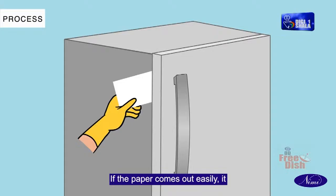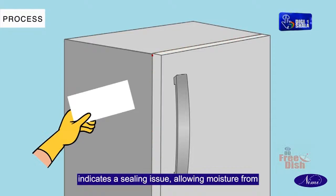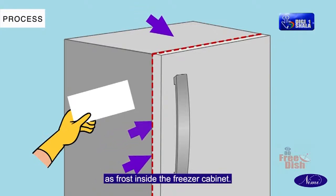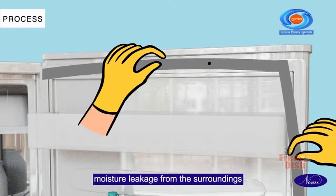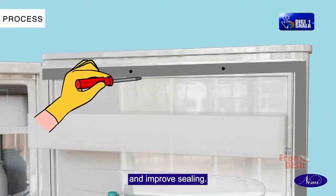If the paper comes out easily, it indicates a sealing issue, allowing moisture from the surrounding air to enter and deposit as frost inside the freezer cabinet. Change the door gasket to prevent moisture leakage from the surroundings and improve sealing.